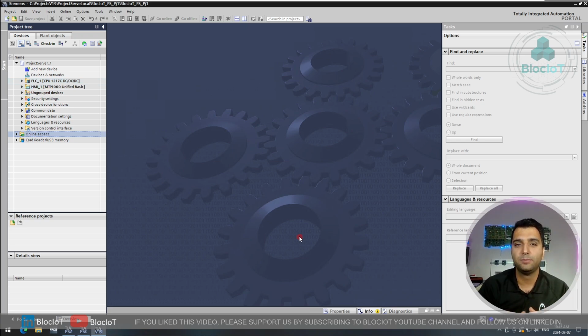So let's look into the administration console, and just for practicing, let's roll back the project to the revision where the 10-inch HMI was added. So we basically want to remove this HMI from our project. Let's see how we can do it. I have to repeat myself: because we are using the exclusive mode, or the free version of the TIA project server, we have some limitations and there are some more steps to be done when you want to roll back the project to a previous version.